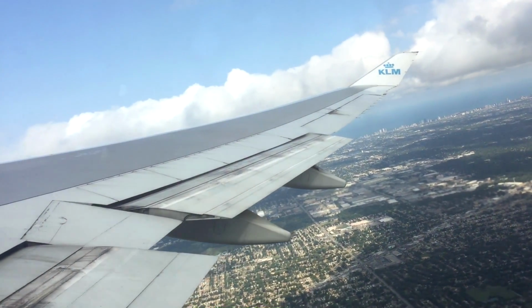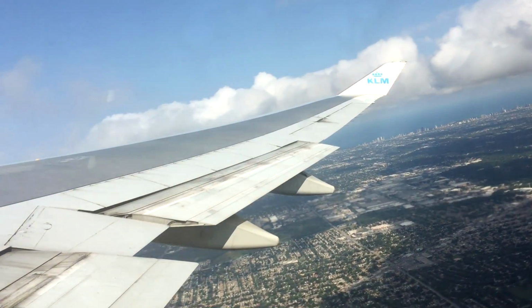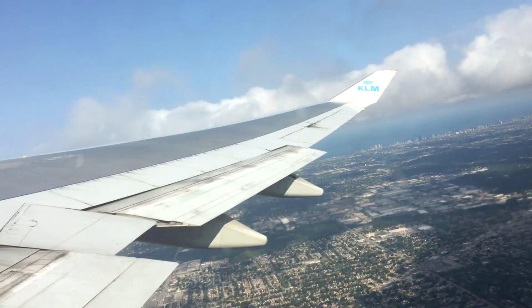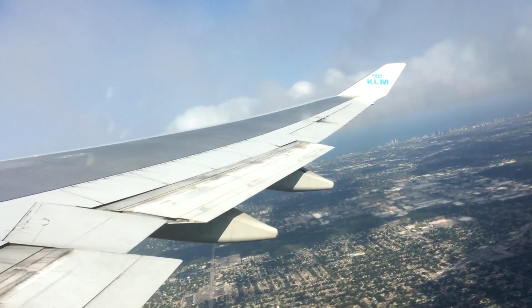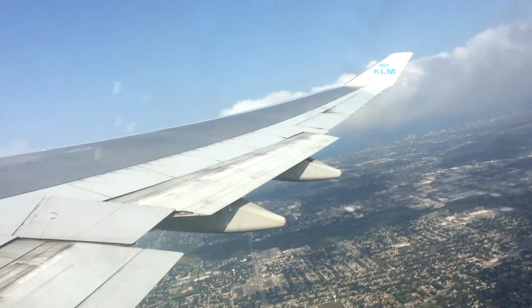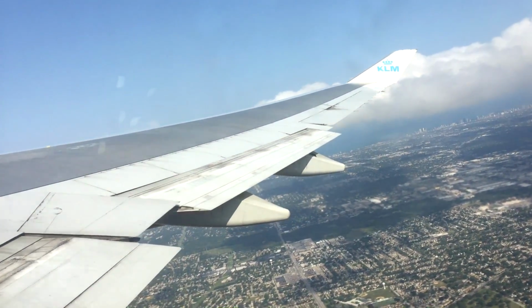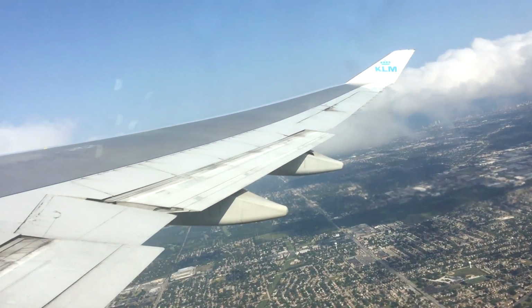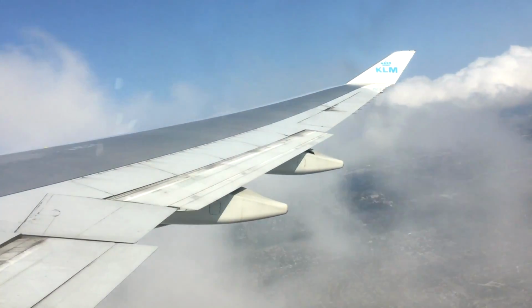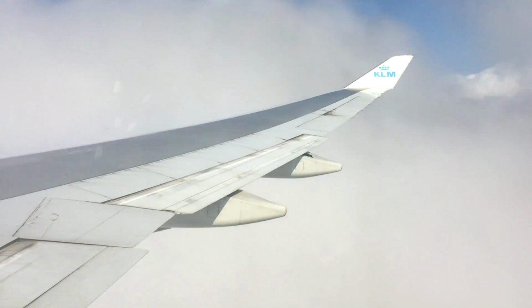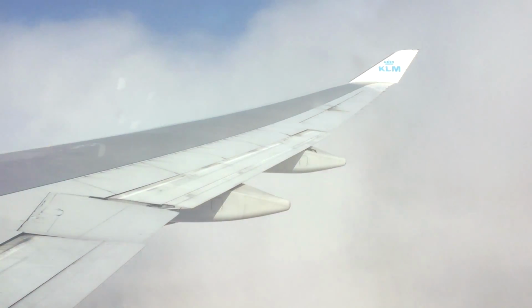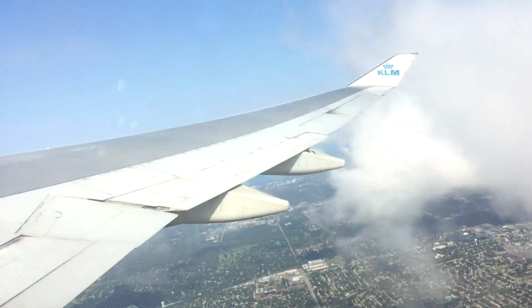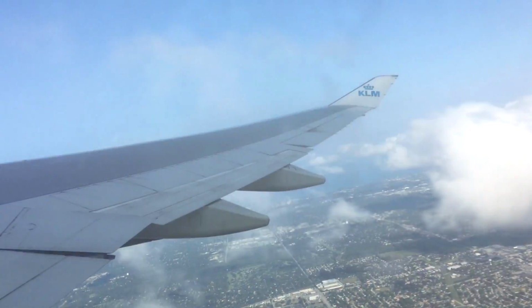Now actually, if you've ever flown from Europe to the US and back, you will notice that your return flight to Europe is a lot faster, because thanks to the jet stream and thanks to these NAT tracks making use of the jet stream, your tailwind component is huge. Sometimes the aircraft really fly close to the speed of sound when looking at the ground speed. Of course, the true airspeed is different because the air mass is moving as well, but some high speeds are achieved there. In general, those flights are therefore a lot shorter in time.